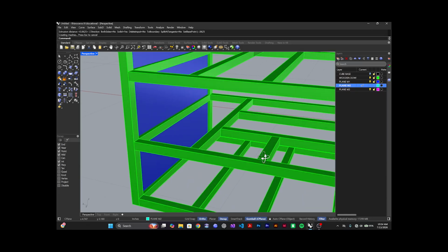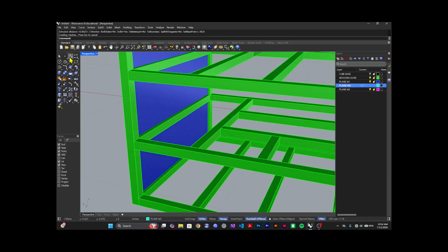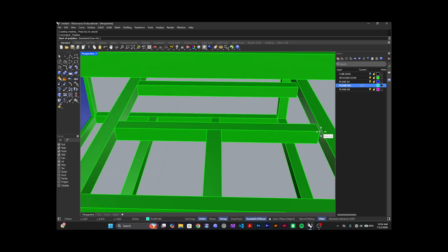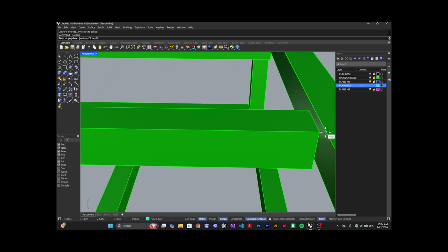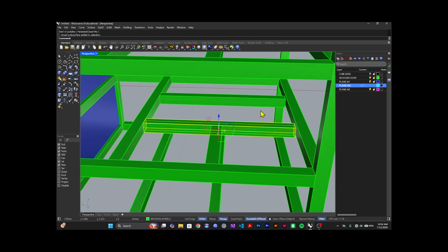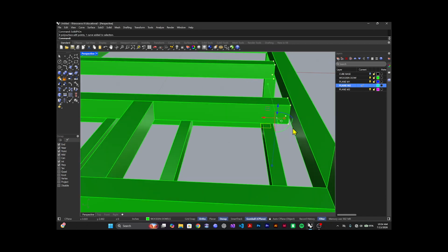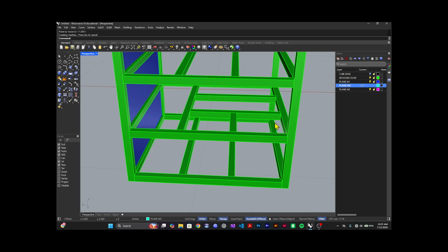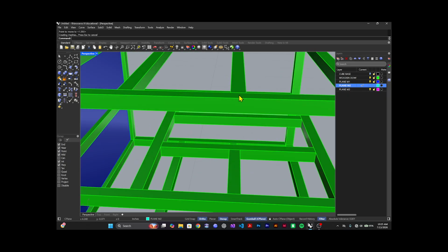So now let's say that I want a surface again. We can do polyline. Let's say that I have a plane right here. I'm sorry, this should be connected, but let me fix it really quick. So again, both of them, and then solid points on. We select all the points, and then we type move, and we just connect them right there. That's what we want. That's how you guys can easily edit the lengths of your structure, right?